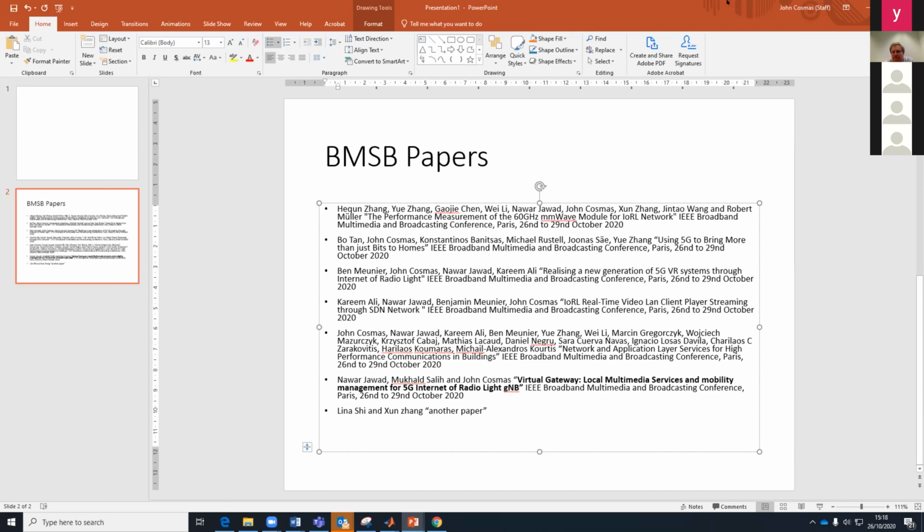So in retrospect, we originally had envisaged the millimeter wave and the visible light systems to sit side by side, but because the millimeter wave systems can have bandwidths up to 400 megahertz, whereas the visible light at a push can get to 20 megahertz bandwidth, we had a problem with the remote radio light head controller not being able to provide both without considerable FPGA processing power.